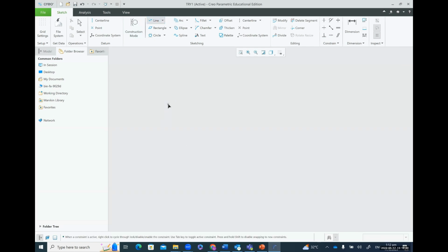First, let's assume that I'm going to create a horizontal line. Okay, and then I create another horizontal line over here. Now these two lines are not equal lengths. To make sure they are equal, one thing you can do is manually enter the dimension of each line, or you can use this constraint. Okay, equal constraint.